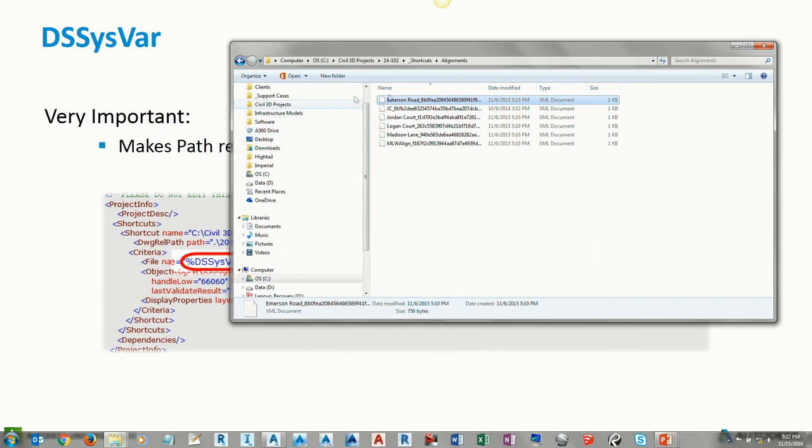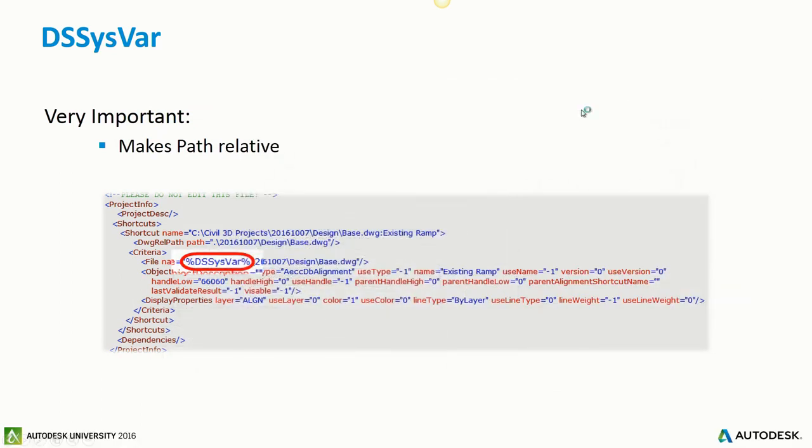The other use of that custom launcher is to set profiles. Have you guys heard of ARG file? Anybody? Profile, AutoCAD profile, right? AutoCAD profile and desktop shortcut, there is a /p, and you all know about that. But the custom Caltrans Civil 3D launcher sets a profile. Apart from other things, it does one very important thing. If you are in survey department, it will set your QNew variable. You all aware of that? The quick new command. Anybody not know QNew? It sets the profile ARG, which will set the QNew to survey template or design template.